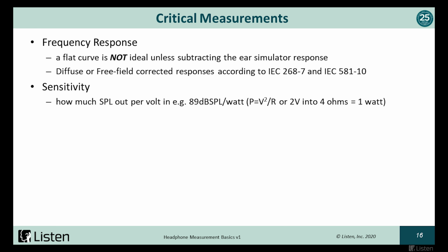Of course, we want to measure sensitivity because first of all, we want to make sure that the left and right ear are pretty close in sensitivity. A 1 dB difference between left and right ear will shift the image. We also care about the sound pressure level, so we want to know the sensitivity, and if it's a small smartphone with a small headphone amplifier, it's only limited in how much power it can produce. So more sensitivity is generally better. But again, we're going to wireless devices, so we have even less power inside the headphone amp chip.